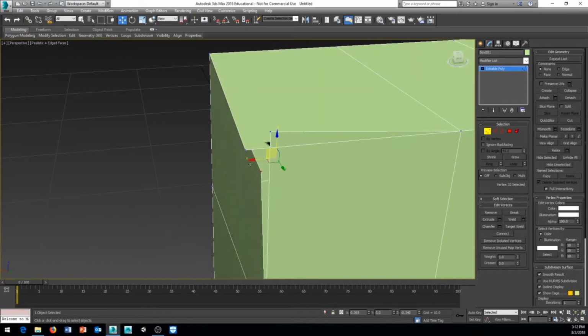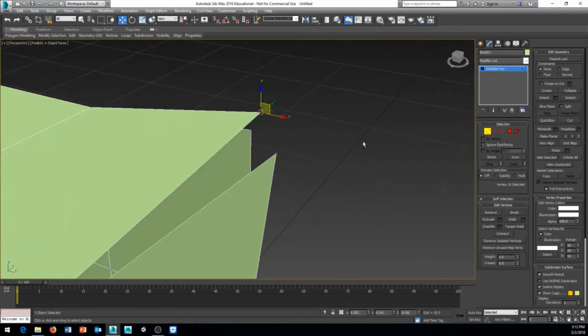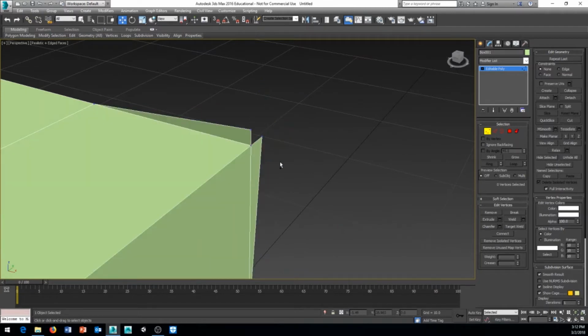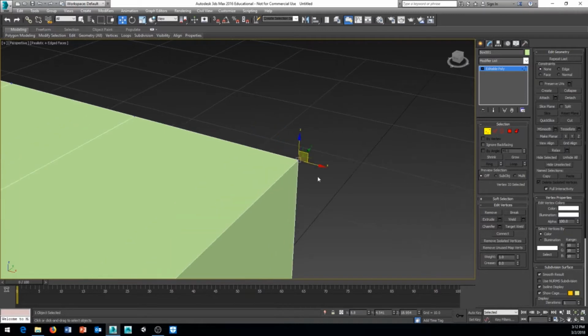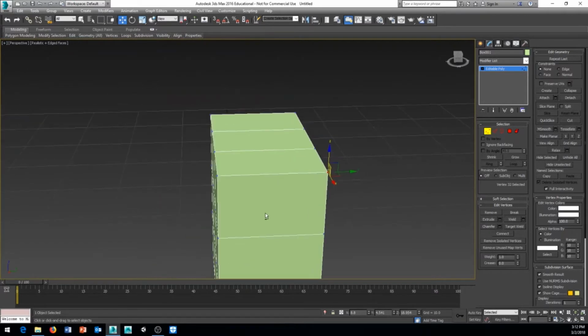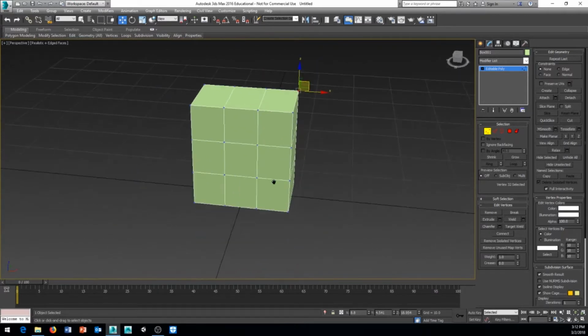So if I move this down here, move this up here, then my vertices, even when they were all together after I broke them, this is technically 3 vertices. If I come in and weld it, I can see how before I had 34 vertices and now I have 32. So now this is again watertight.